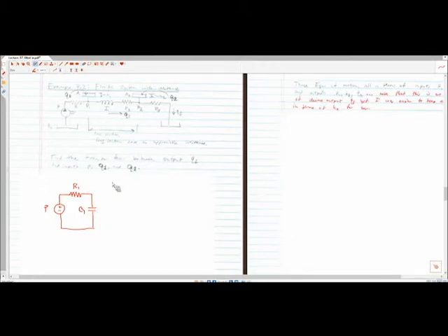The next leg is a little more complicated because we have inertance associated with it. We get to our next tank, C2, and then we look at the very end. And this is R3. All right. And I've missed a critical component of this that we're going to throw in a second. But just to label these, inertance, this is then R2. We have our two different tank capacitances. And then the next thing we have is fluid dumping into the tank as well.